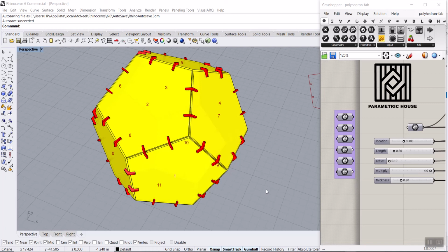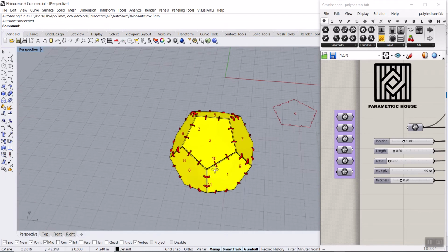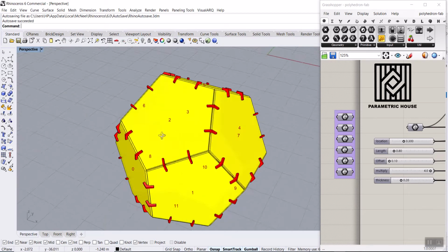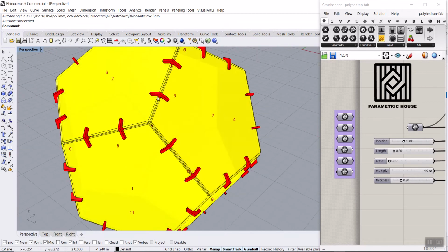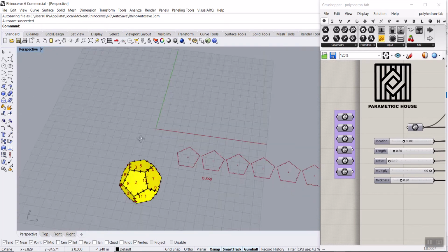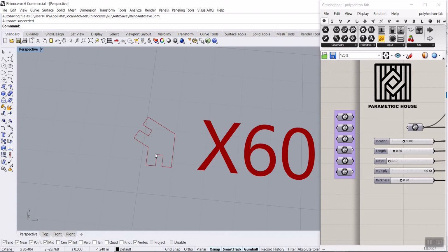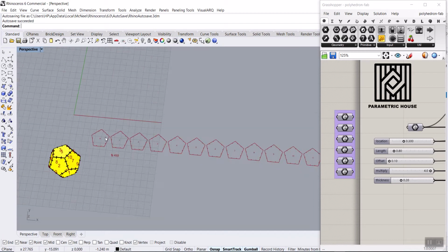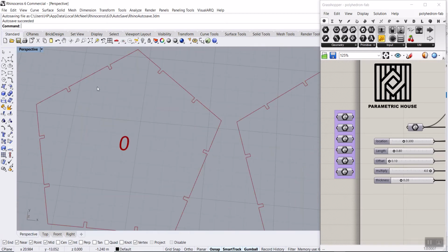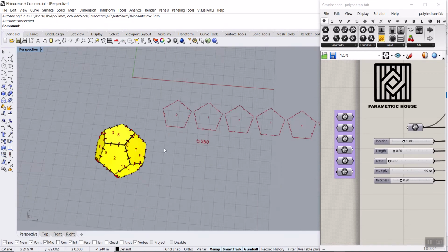In this premium Paracourse lesson, we want to fabricate a polyhedron in Grasshopper. Actually, we're going to define different polyhedrons and make these connections in Grasshopper, then put them on the ground. You can see that we need 60 of these connections, and also all of these faces are the same for this one, so you can use this curve for fabrication.